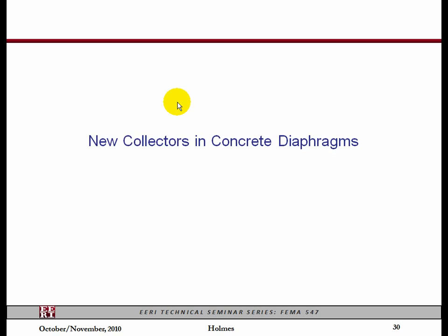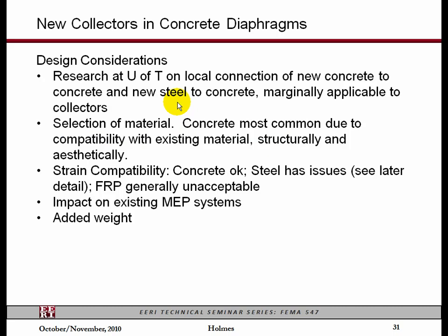Collectors in concrete diaphragms. This is a diaphragm issue, but we've put some tips into the concrete section because it comes up in every building. There was this research at University of Tennessee on the local connection of new concrete to old concrete. Again, there are certain things that do not work well, but for a collector, you've got to worry about strain compatibility.